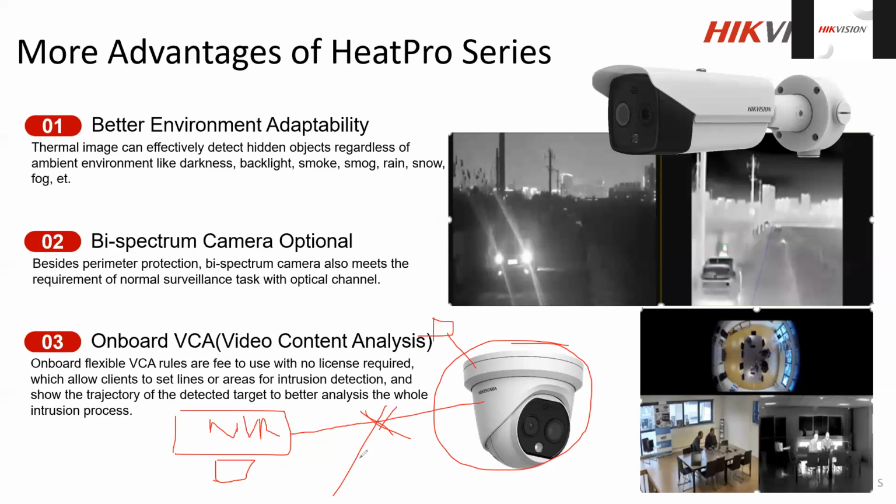So even this connection is disrupted unless it is PoE. These cameras can be powered with PoE. So what we recommend is for you to definitely have the backup power. So in either case, it can have a redundancy of PoE and the power supply. So what will happen is if the power supply is dropped, PoE will take over. If the PoE is dropped, obviously the power supply is there.